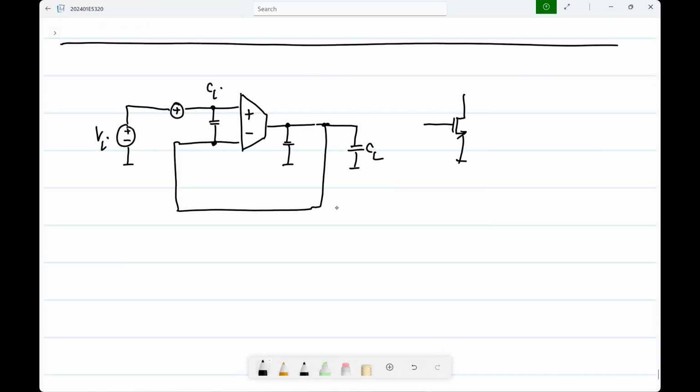CL, this is Ci and Co. And I had said that, just for simplicity, Ci and Co are both gm by some transit frequency omega t, where omega t is a parameter of the process. Okay, I'll explain what that is with the transistor. In fact, that's commonly used to characterize the process. But the point is, the higher the omega t, the smaller the parasitic capacitor for the same gm. Okay. So now what was the result of this?